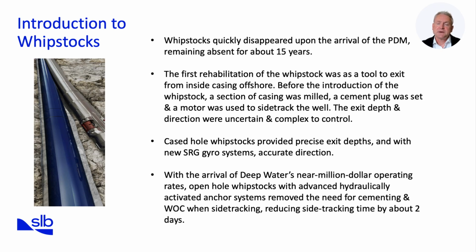If the inclination is below 7 degrees, the MWD relies on magnetics, which are of no use in casing. Therefore, a gyro will be needed instead. This tends to be more time-consuming.